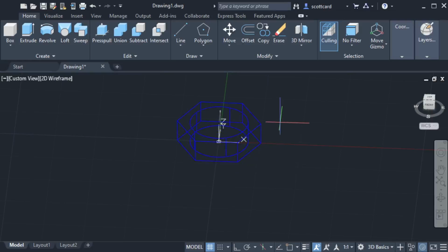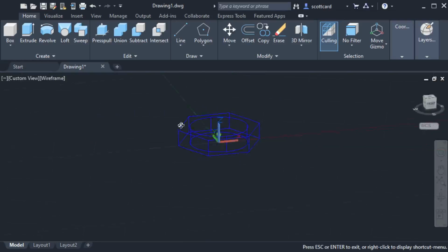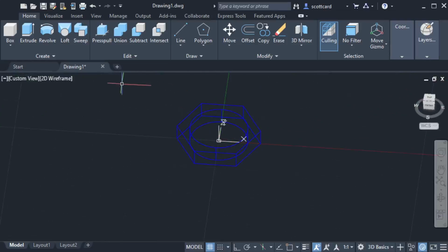And it doesn't really give us a dimension, but I'm going to pick something. Now I know that the thread pitch is 1.5 millimeters, so let's make it 3 millimeters. That'll be, let's go with 0.2 of an inch. Probably good enough. And this is reasonable.